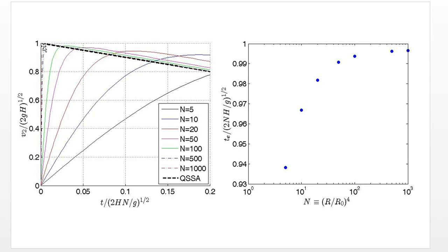As soon as that hole is opened, it assumes the velocity is immediately equal to the square root of 2gH. In reality, as we've mentioned a couple of times, there is this transient period it takes for the velocity to adjust, and that's what's captured in the actual numerical solution here. But once again, when the hole is 1/3 of the size of the tank or smaller, there's very, very good agreement with the quasi-steady approximation.